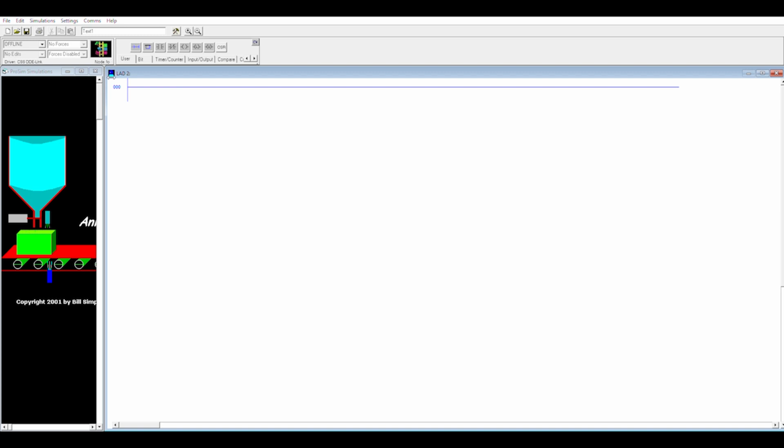The second thing I'm going to deal with is if I have a look at a rung. A rung is very much like a circuit using relay logic. We need a power rail and a return rail. We don't have a return rail visible. In fact, the right-hand section of this is completely missing. If I was to try and program there, the program would occur, but it would not display. We want to be able to see everything we're doing.